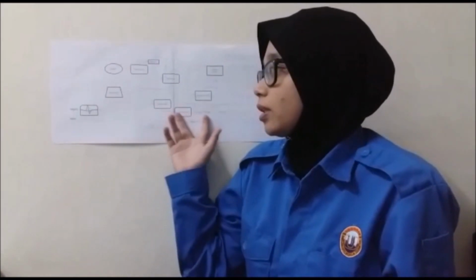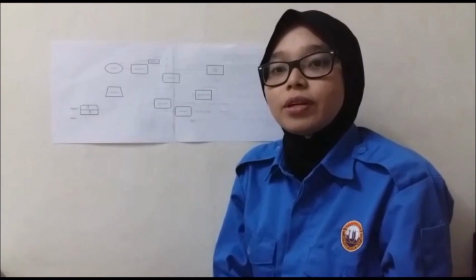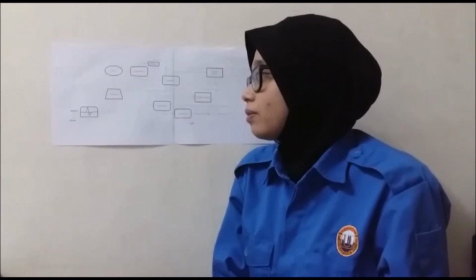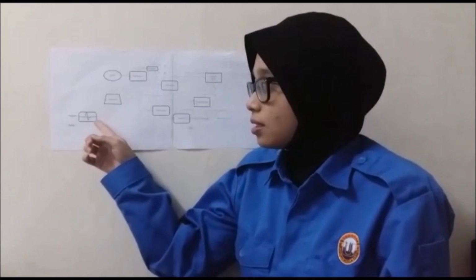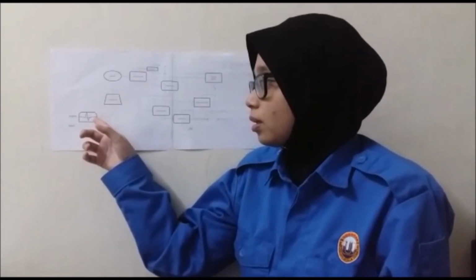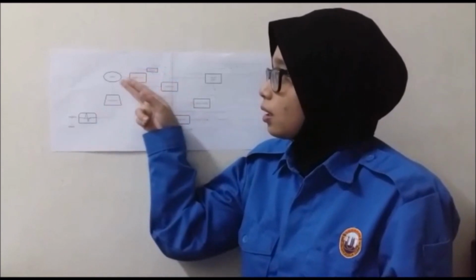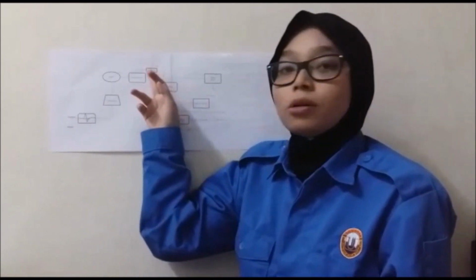I will proceed with this slide with the explanation about the process flow diagram. This is the process flow diagram for this petroleum refining process. First and foremost, we begin with the entry of the feedstock recycle into the pyrolysis. Then the product will undergo a compression process, quench process, and then go to the demethanizer process. At the demethanizer process, we split into two: a cold box and the deethanizer.